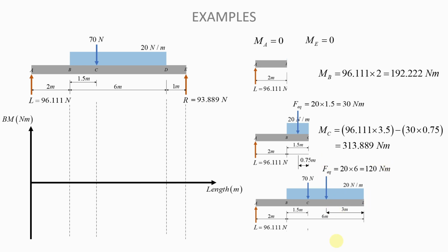Okay, and so once you have it like that, you can then calculate the moment at the cut. Notice again that 70 and 120 newtons, these two forces will both have an anti-clockwise moment, and therefore it's negative. So when we're doing the sum, there are moments we will put a negative sign before. So we sum all the moments at the cut at D, and this is what you should get. And the magnitude of the moment at D will be 93.888 Newton meters. Okay, very important.